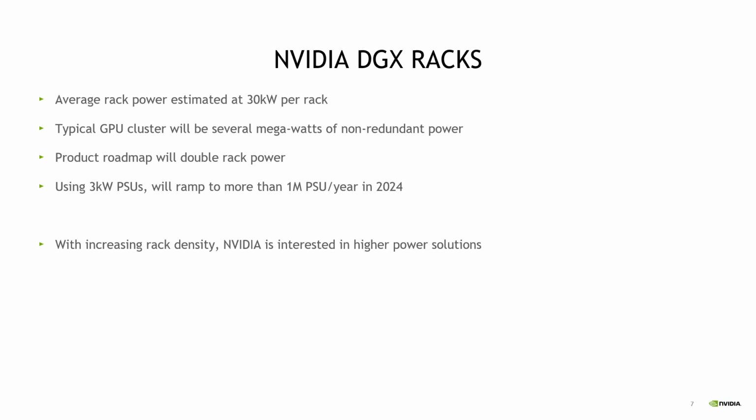The trade-off. You also talked about the 200 to 277. Are you guys seeing that in the U.S., you still got a lot of 208, so you need even larger amperage? Is that what you guys are designing to, assuming 60 amp 208, and you don't think the U.S. is going to change to 415 240 anytime soon?